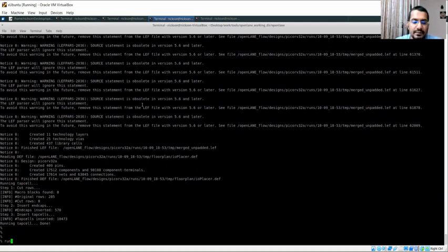Global placement is basically a coarse placement, and there is no legalization happening. Legalization happens in detailed placement. So what is legalization? The standard cells are placed in standard cell rows. They have to be exactly inside the rows, they should be abutted with each other, and there should be no overlaps. This is what legalization is. Legalization is more required from the timing point of view. These are some concepts which you would want to explore.